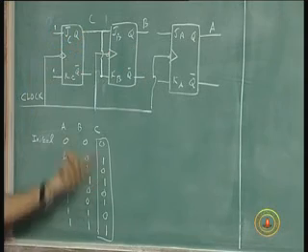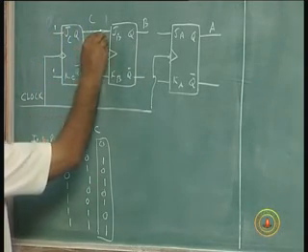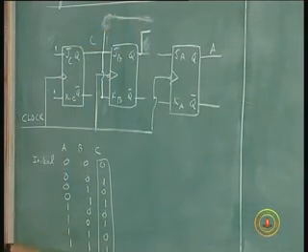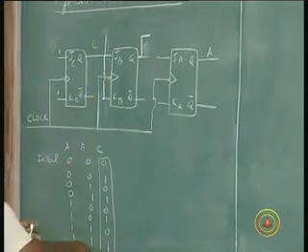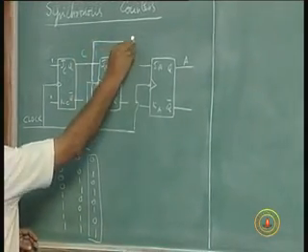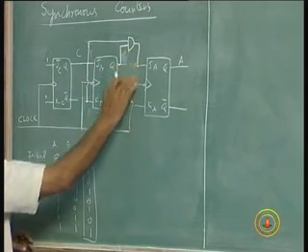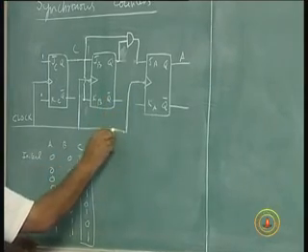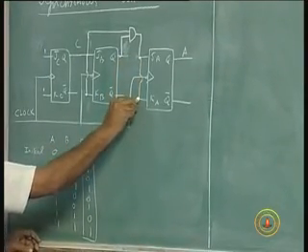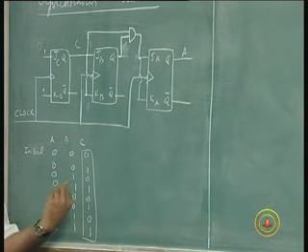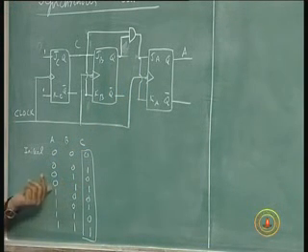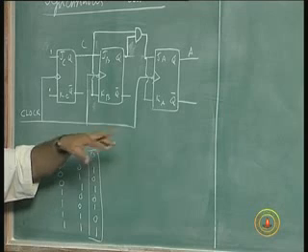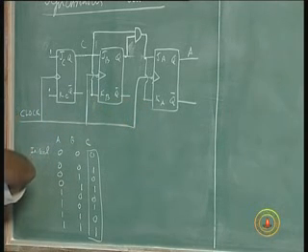So what I am going to do is to take these two into an AND gate. So when both B and C are 1 1 at the 4th clock pulse, immediately thereafter J A and K A become 1, but the clock pulse has gone.